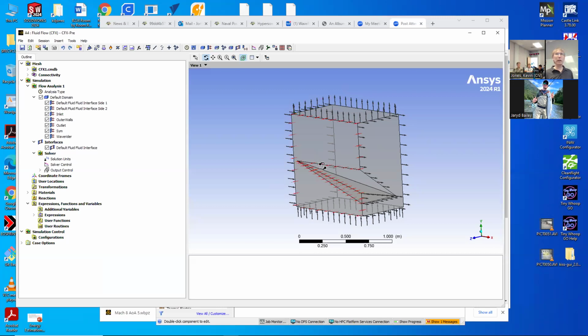I can't draw on the whiteboard. Do you remember when we first introduced supersonic flow and we looked at the quasi one-dimensional channel? We said it can only go sonic at the narrowest part of the throat. And there was also a brief discussion saying that there can only be one throat. If you put a narrow region downstream, it'll never go sonic upstream. That'll be the new throat.